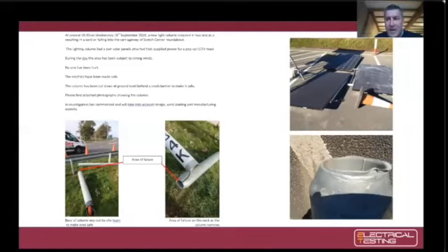So it's not a spring loading bracket, which would allow the panel to move and the wind to disperse around it. So that solar panel has taken the full force of the high wind event, and the wind event was obviously that aggressive that it snapped it at the shoulder. So you're looking at a 4 or 5 mil column that's newly manufactured, that will snap in half when it's applied a wind load that's that considerable.